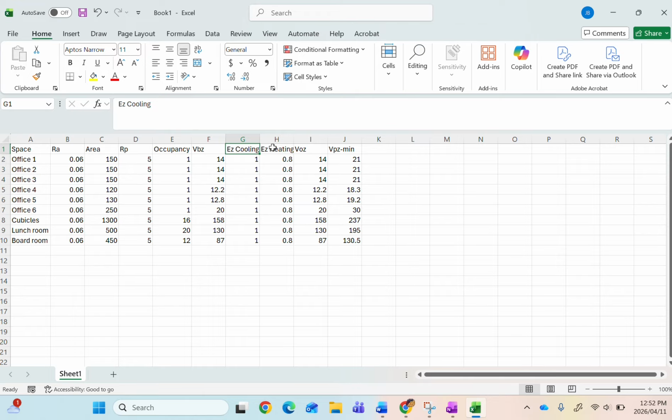So if we're using one duct system but have two potential situations, we want to make sure that we're getting the proper outdoor airflow, which means we're going to have to meet the more strict situations if we're not able to modulate outdoor air, which in this case we'll assume we can't. So what we do is look at both of these values and take the most conservative calculation.